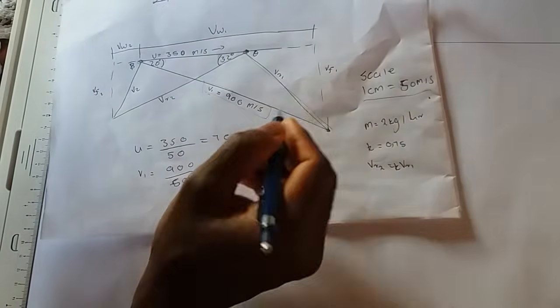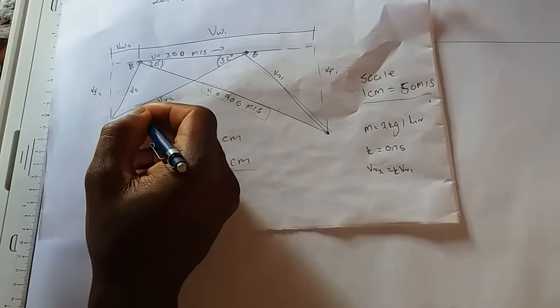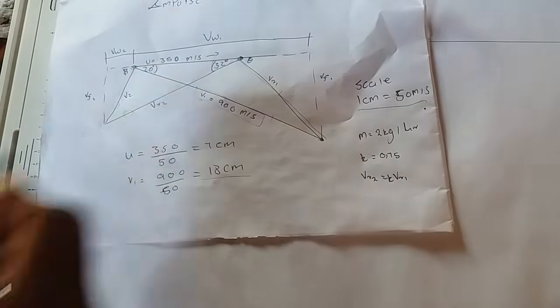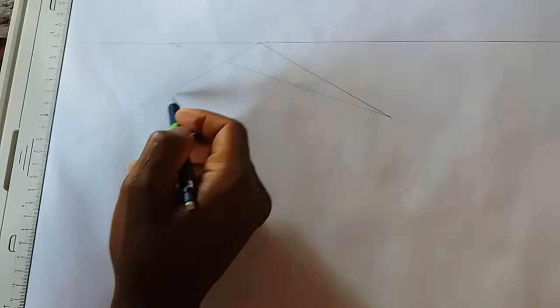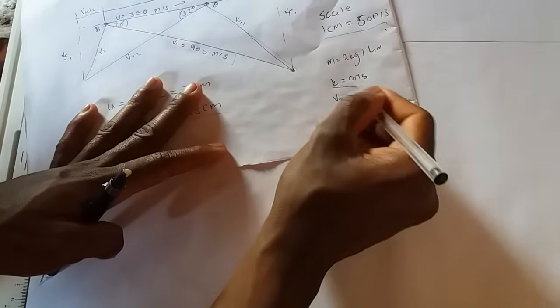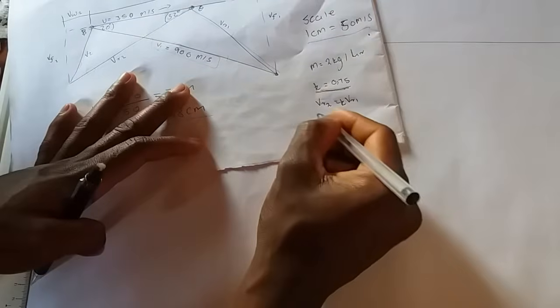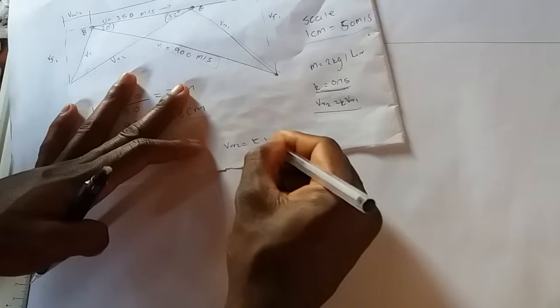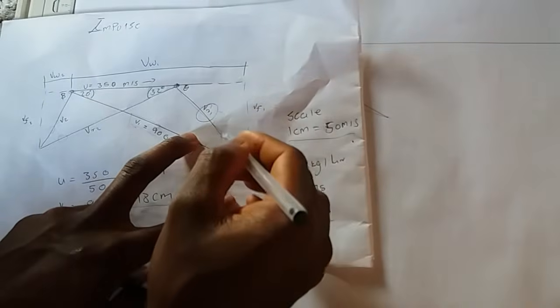And then now we have this, we do not have this and this. We do not know the measurement of this line, but we know its angle. We do know the point is going to be somewhere here, but we don't know exactly where. And then that's where we will use this value, which is our K. There is the formula like this, which is VR2 is equal to K times VR1. We already have this line, which is VR1. We have just constructed it.